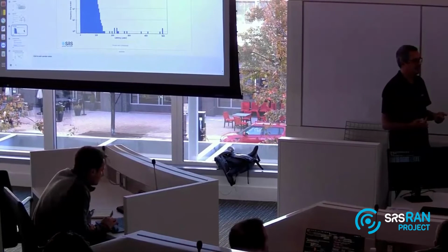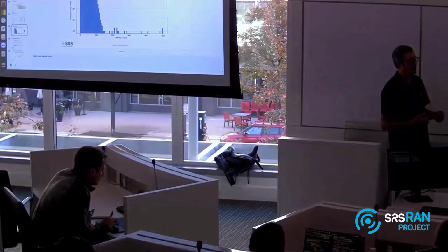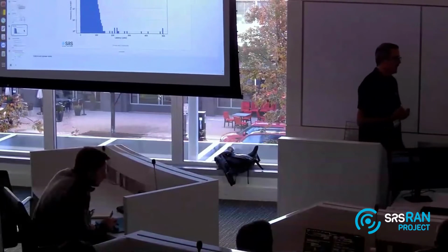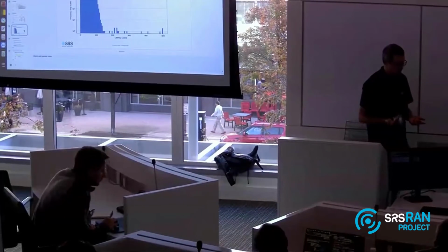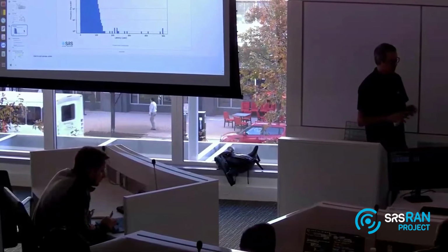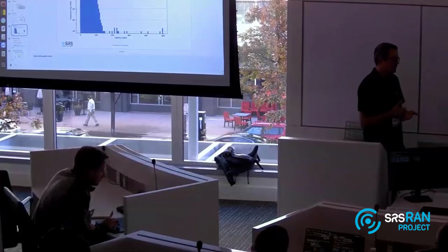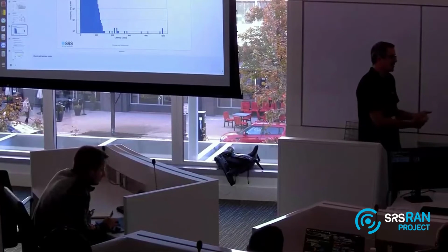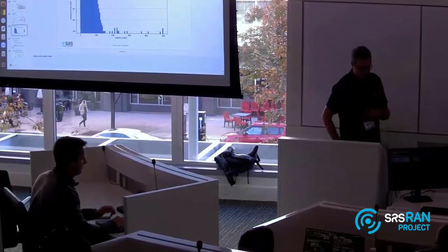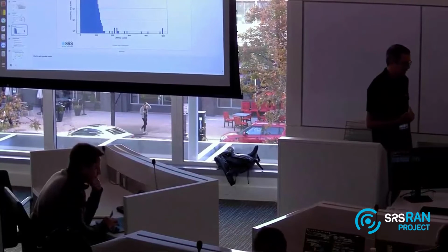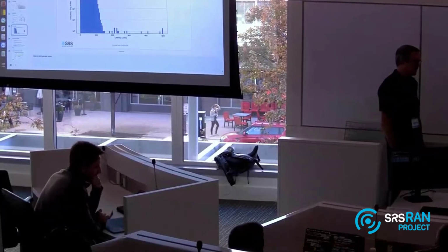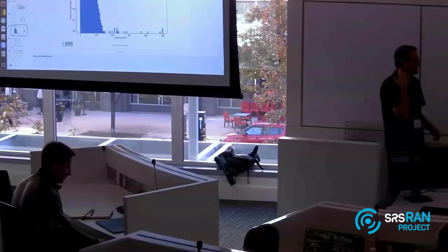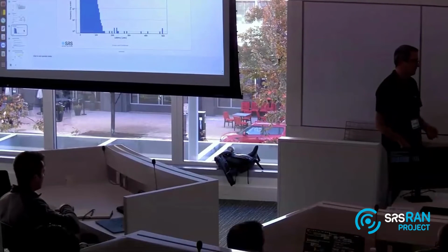I have the impression that sometimes a task with lower priority is preventing a task with higher priority from running because it's holding a mutex or something like that. After experimenting a lot and defining these configuration file options to let everyone play, we found that the operating system's decisions were the best. But I will go through this configuration file later, and I invite you to play and see if you can find better solutions.